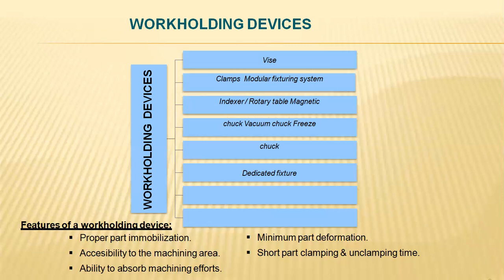So in the semi-automatic case, there is some time lag in order to change the work part to be fixed and removed from the jigs and fixtures, and tool bits changing within the tool post for different kinds of operations: facing operations, slotting operations, reaming operations, finishing operations, etc. Hence, it takes much time for manually changing both the work part from the work holding devices and the tool from the tool holding devices.